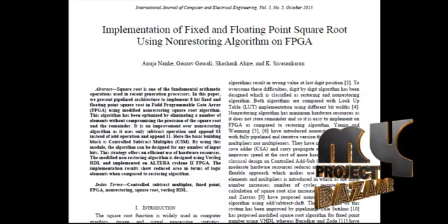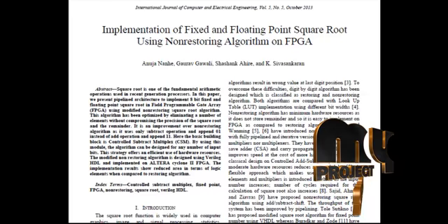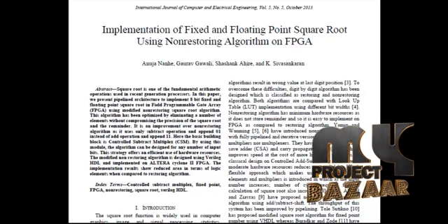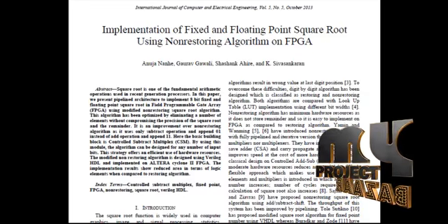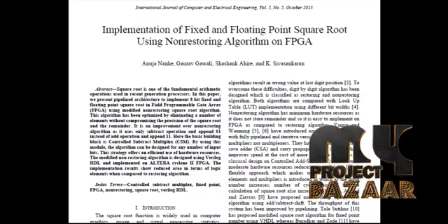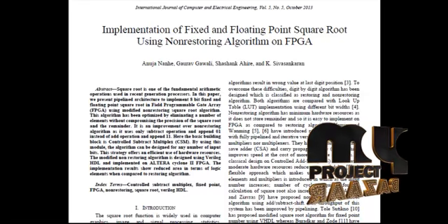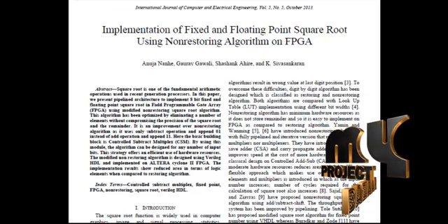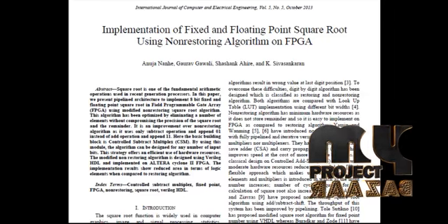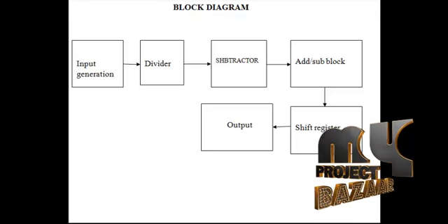For division, the sign bit of the result is the output of XOR logic of the two sign bits from the operands, and the exponent is obtained from the subtraction of the divisor exponent from that of the dividend. For square root, the sign bit of the result should be 0. Otherwise, if the operand is negative, an exception is raised. The exponent for square root is the floor function of the half operand exponent.